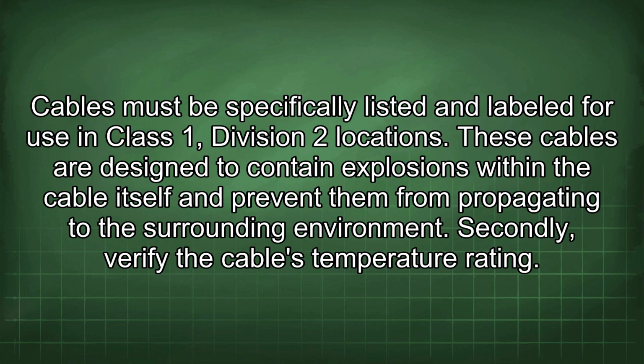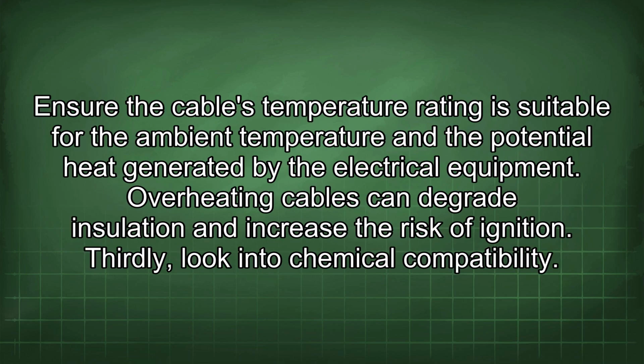Secondly, verify the cable's temperature rating. Ensure the cable's temperature rating is suitable for the ambient temperature and the potential heat generated by the electrical equipment. Overheating cables can degrade insulation and increase the risk of ignition.